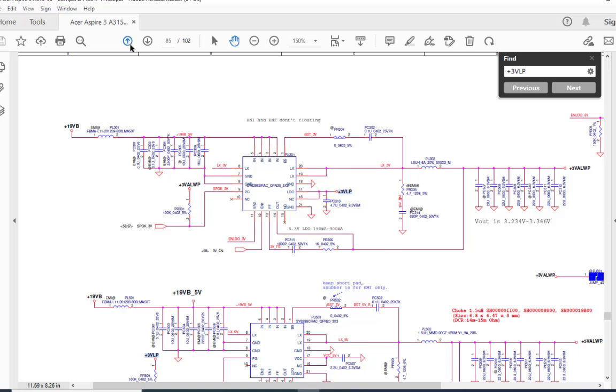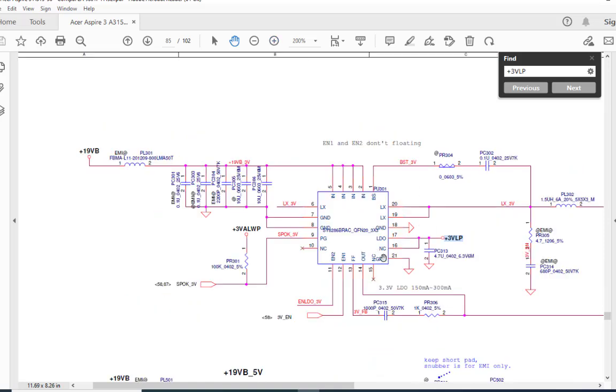Okay, so now we'll go back, come here and check how much voltage. We have to check 3 volt. Now if the 3 volt is not coming, then we have to go back and check this input, because this chip is a single chip buck converter. That means in this chip the buck converter is there within the chip, MOSFETs are there, and a linear regulator is also there.